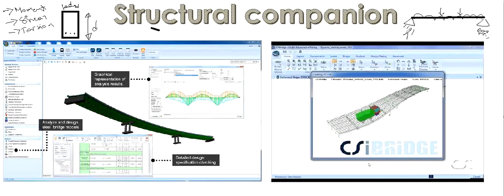So if you did a very bad estimation or calculation of the reaction, it means your determination of the moment, the shear force, and the torsion will also not be correct. To determine moment, shear forces, and torsion, you need to know your reaction. That's why reaction is maybe the most important calculation from a structural engineering point of view.